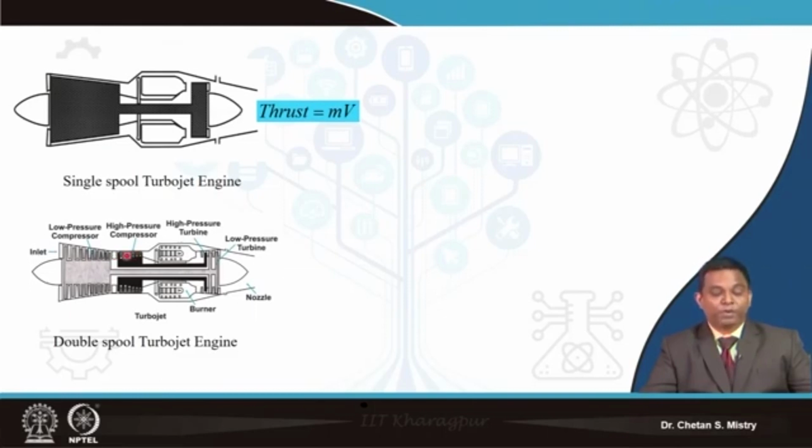Now this high speed rotation is giving the reduction in the number of stages, which we discussed earlier. Here also, this is called the HP compressor. Do not get confused with the terminology of HP meaning high pressure generation. No, it means my operating pressure is higher. So we have this kind of configuration that meets the requirement of power generation for the generation of my thrust. A similar kind of configuration may be used for land-based power plants. So in order to avoid the limitation of the single spool, we are moving to the double spool configuration.